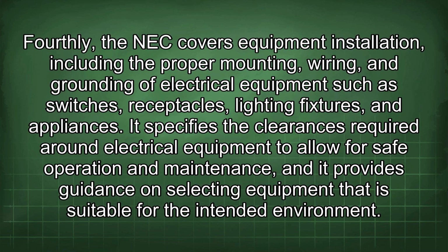Fourthly, the NEC covers equipment installation, including the proper mounting, wiring, and grounding of electrical equipment such as switches, receptacles, lighting fixtures, and appliances. It specifies the clearances required around electrical equipment to allow for safe operation and maintenance, and it provides guidance on selecting equipment that is suitable for the intended environment.